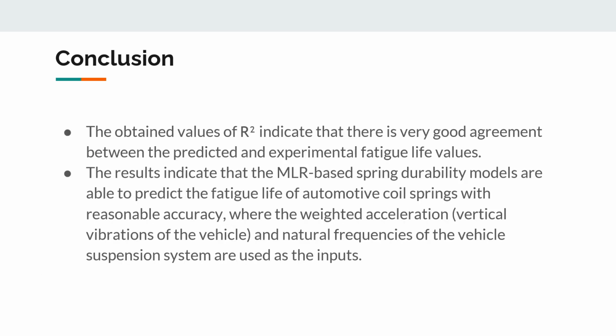So, in this study, multiple linear regression based spring durability models were developed based on the Coffin-Manson, Morrow, and Smith-Watson-Topper strain life models to predict the fatigue life of automotive coil spring and vehicle ride quality. The R-square values obtained from the experiment and from the multiple linear regression based spring models are listed, and they indicate that there is a very good agreement between the predicted and experimental fatigue life values.